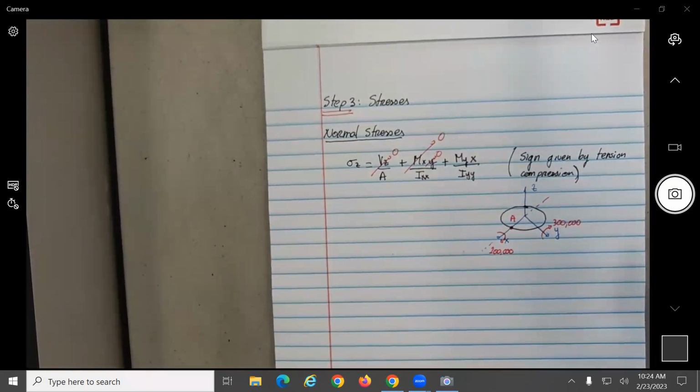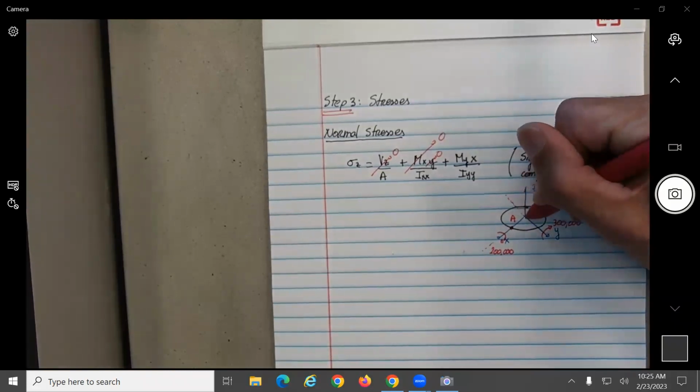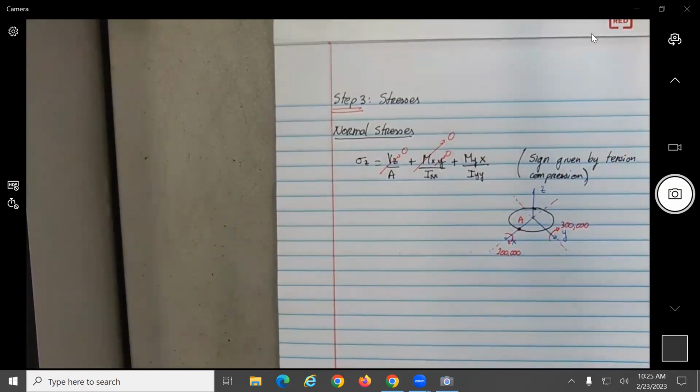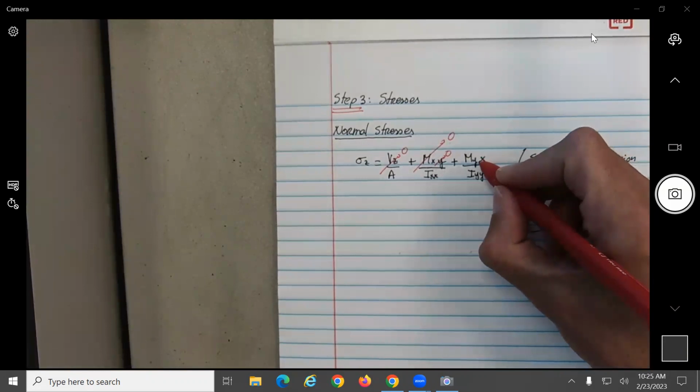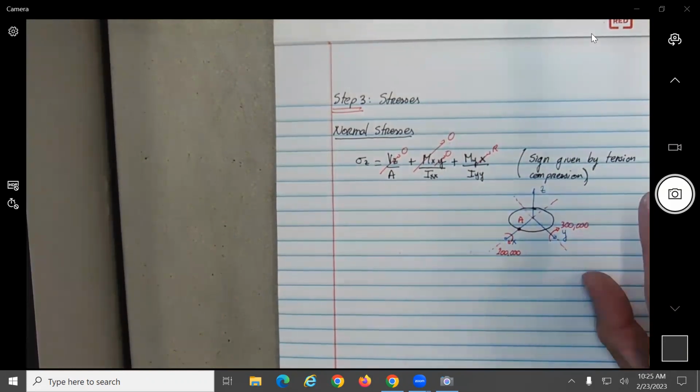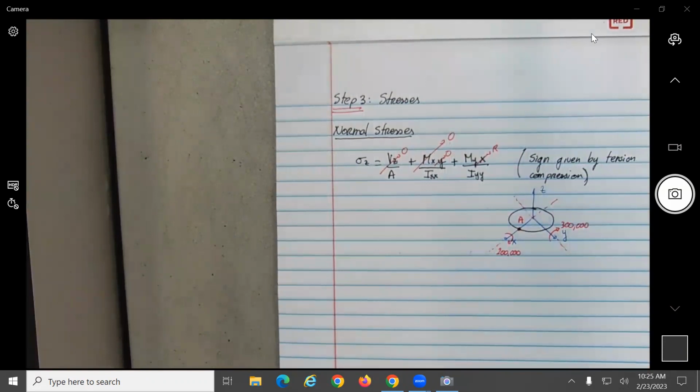Okay. All right. Now, this point over here, now for the My, this one will be the neutral axis, which is the y-axis, no? So what would be the distance x? What would be x? R. Okay, r. Now, this will be creating a bending in that direction. So point A will be in tension or compression? Tension. Do you agree? Yes, okay.